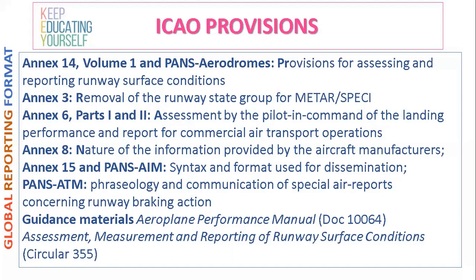After 8 hours, we have to issue a new SNOWTAM. Whenever the aerodrome operator issues a new runway condition report, if it is wet, it will be given only to air traffic services. Other than wet, it has to be given to the AIS section for issuing a SNOWTAM. We will discuss this again.